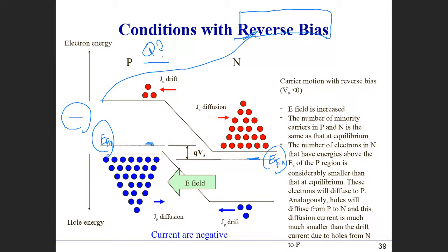Now, for this particular case, when you apply the reverse bias in the p-n junction diode, as you can see, on the P side, this Fermi energy level is going up compared to the N side in here. That means that when you look at this barrier, when you apply the bias, you define it as VBI minus the applied bias. Since the P side is negative bias, your barrier, this one, is larger than the case in thermal equilibrium, right?